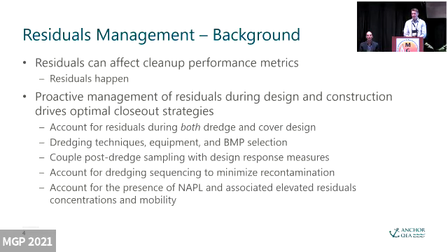And as I said, we know that those types of residuals will happen. We know that once we go out and do the dredging at our site, the surface will be impacted. We'll have some high concentrations. We may have some mobile NAPL. So we wanted to get this out in front of the agencies early in the process so that they understand that these concentrations will be there, as we know.